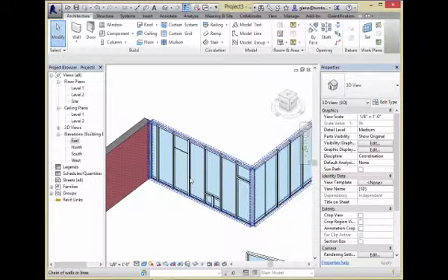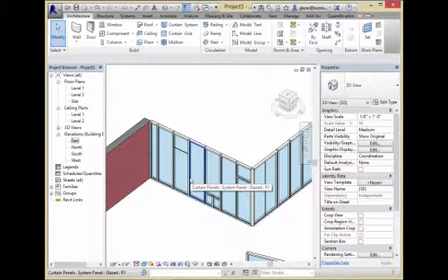I'm going to tab once. That got the chain of walls. Tab again. Okay, that got the panel to the right side. If I tab again, I was going to guess it would get the panel there, but it got the panel to the left side. This tabbing rotates you through the different options. When you get to the thing that you want to change, select it.